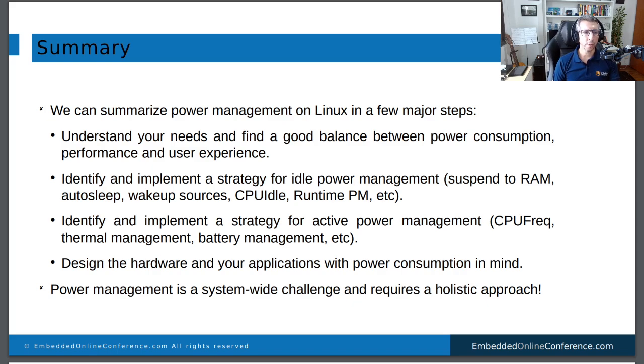And then as soon as you gather the requirements and understand what you want to do, you have to define a strategy for power management. Do you want to do idle power management? If so, what kind of idle power management do you want to do? Do you want suspend-to-RAM? Do you want auto-sleep? What are your wake-up sources? You have to define all of that.